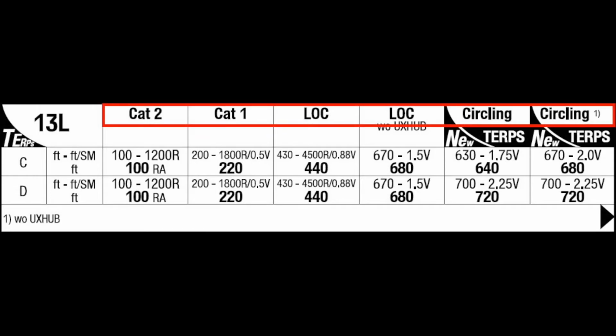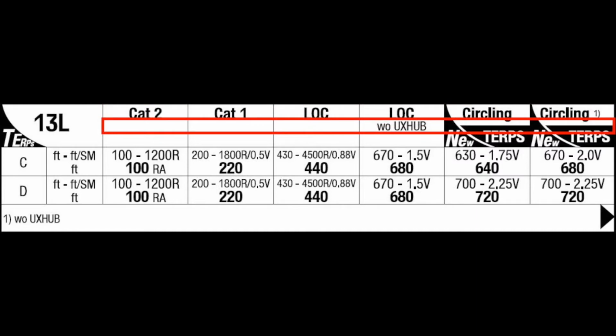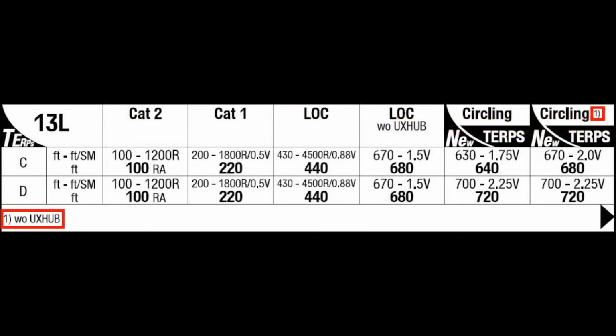The system line shows the main type, the classifier where applicable, and subtypes of the approach to be used. For all precision approaches, instead of the main type, the classifier, for example Cat 1, is shown. The description line is used to bring additional information concerning the approach forward. This information may or may not be accompanied or further explained by a note in the notes section. Minima relevant notes will be shown as required, always underneath within the notes section of the minima section.